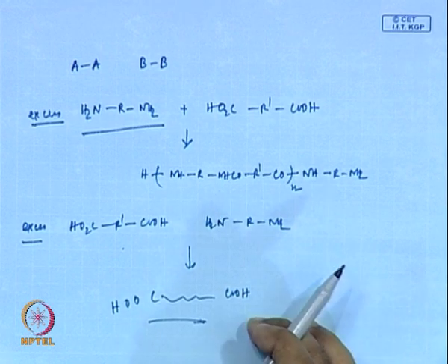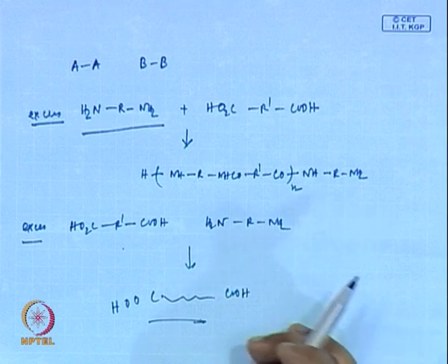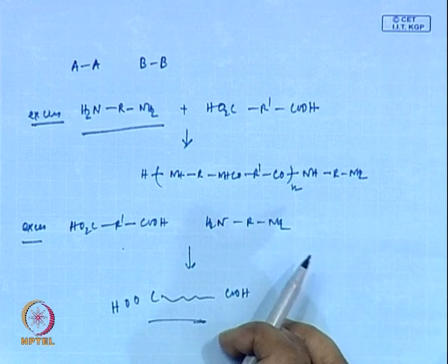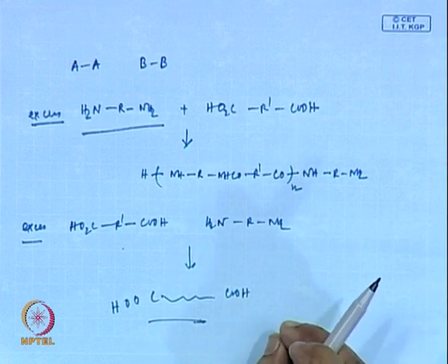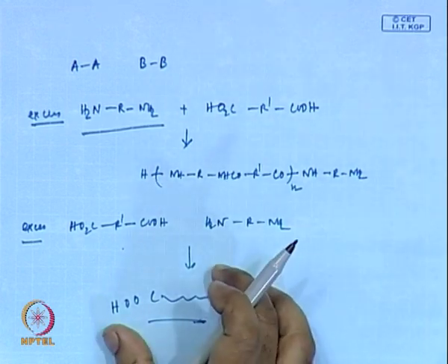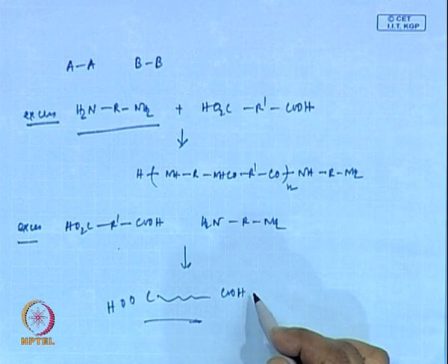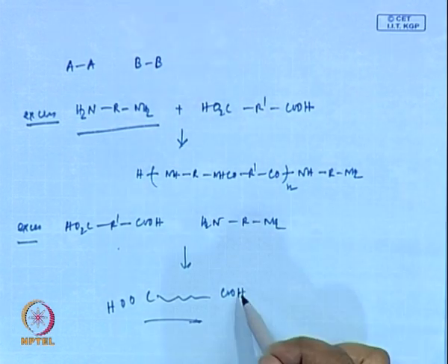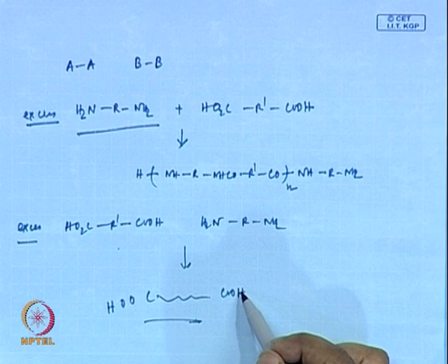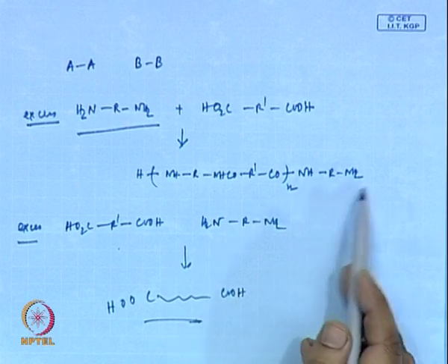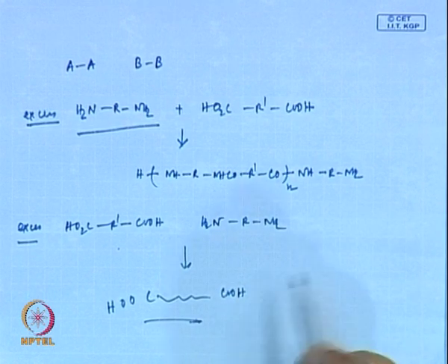So, that your polymers are virtually dead, unless you have something in the reaction medium further. When you take these polymers out and do a compounding and molding step, unless you are adding something from outside which will be able to react with either of these leftover functional groups, it will stay as it is.